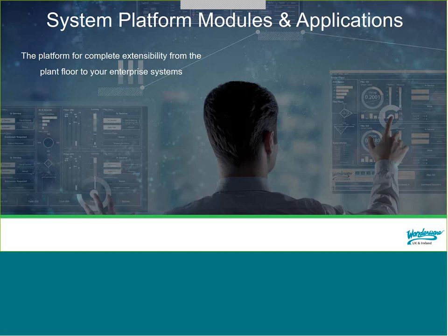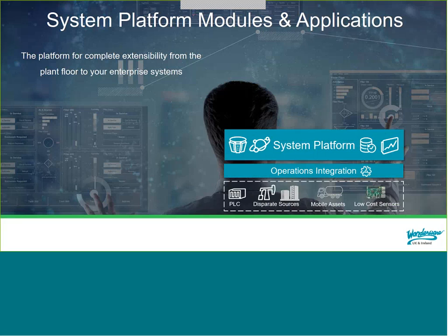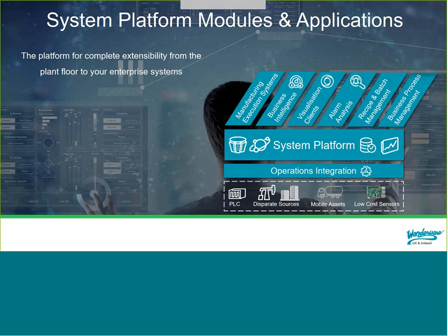So then just lastly on System Platform, I mentioned a little bit about this platform that we can create. So we have our devices at the bottom layer, we have the same integration servers in the middle, we've then got our platform with all of our real-time solutions in there, and then we have our client tools that will make it further extensible. So it might be visualization clients, so InTouch or InTouch OMI, which I'll come on to. A bit about perhaps business intelligence, manufacturing execution systems, getting work orders and things from that ERP layer at the top down to your shop floor, batch management, or even business process management if you want to make it forever extensible.